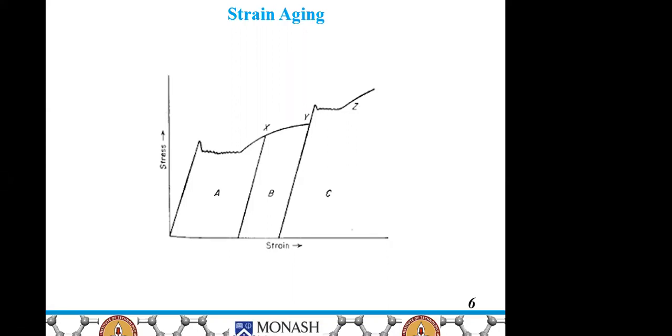If we have given sufficient time for carbon atoms to diffuse back to the place below the positive edge dislocation, then again there will be formation of the Cottrell atmosphere and again there will be yield point phenomena. The reappearance of the yield point is due to diffusion of carbon and nitrogen atoms to the dislocation during the aging period to form new atmospheres of interstitials anchoring the dislocation.